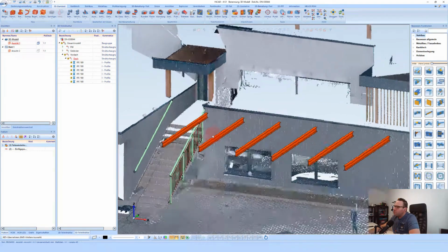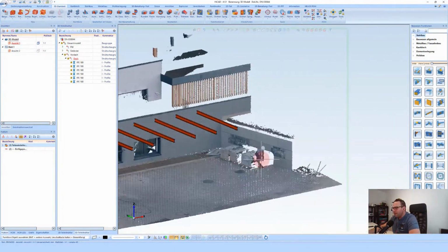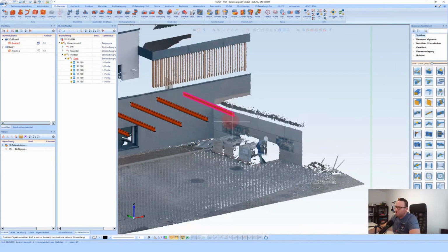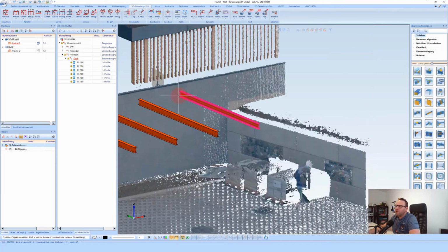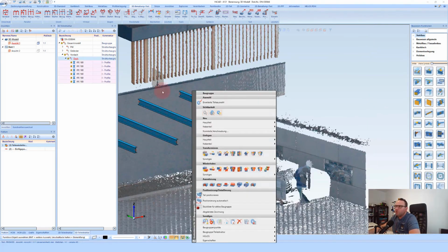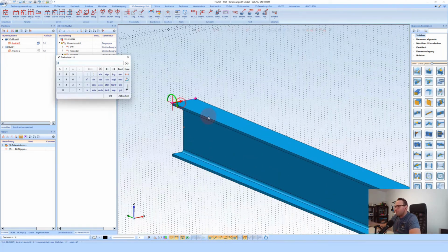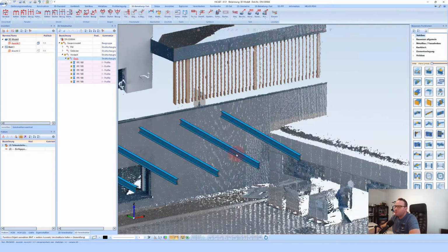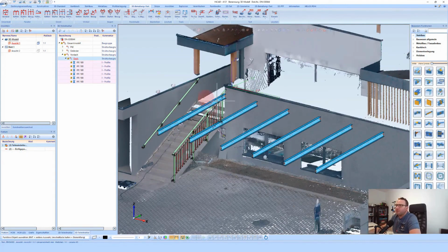So now I just want to define the inclination. You can clearly see here that a little figure has also been scanned. That means I have a reference here right away. I could also define the height dimensions here and measure out the parts, but I see it very nicely here. I want to create a slope here, meaning I want to select this roof and assign a slope along this edge. I say in this case it should be 5 degrees, which means it will be rotated forward by 5 degrees. And I also want to have vertical profiles here.